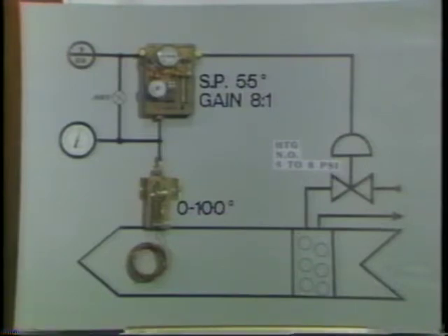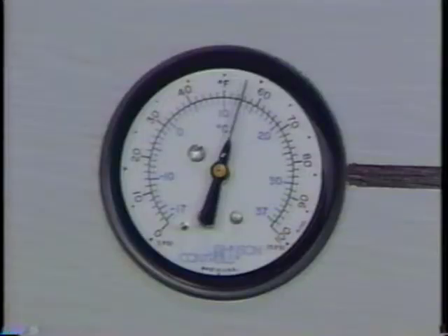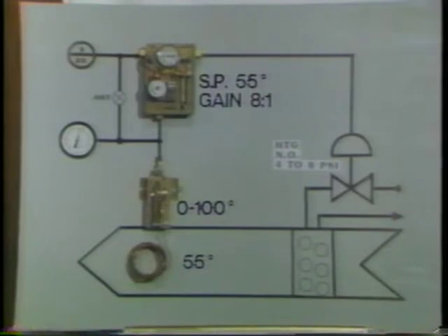The first step is to measure the temperature at the element, and let's say we find the temperature to be 55 degrees. What transmission pressure will correspond to 55 degrees? Following the previous guidelines, we need to know the transmitter sensitivity, which is 0.12 psi per degree. So 55 degrees times 0.12 equals 6.6 psi, plus again the 3 psi starting point, giving us 9.6 psi.